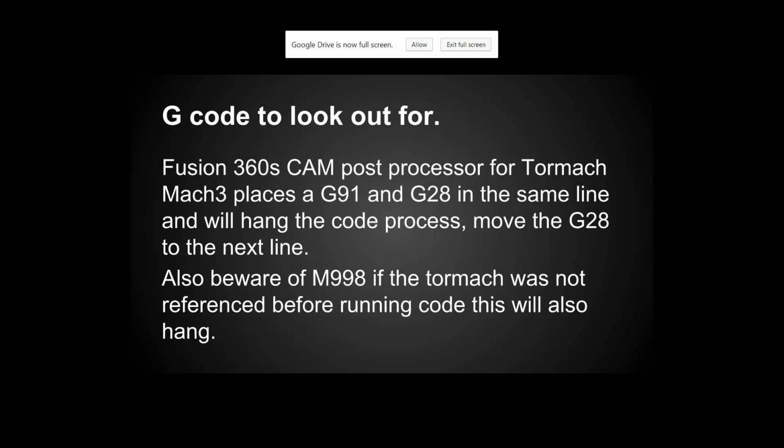Could you comment on 2 things from last week? Yes. So I made about 47 different tool changes throughout the little process, and rumor has it that that's not super efficient. Yes. Now, tool holders for our machine and most other machines, a tool holder for a Tormach is about $30. A tool holder for any other CNC vertical machining center is about $150 to $200. The least amount of tool changes you can do, the better.